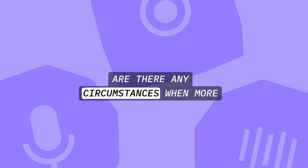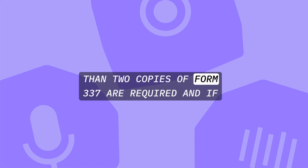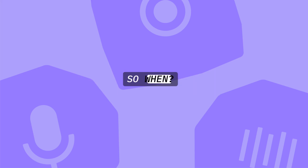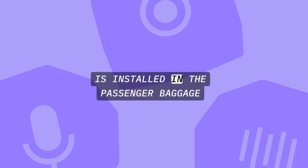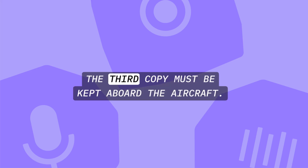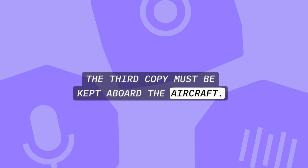Are there any circumstances when more than 2 copies of Form 337 are required, and if so, when? Yes, 3 copies are required when a fuel tank is installed in the passenger or baggage compartment. The third copy must be kept aboard the aircraft.